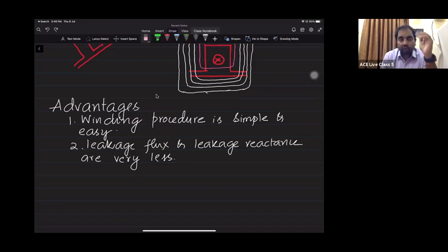So most of the flux lines cross the air gap, link with the rotor core and come back. As such, the leakages are less and the mutual flux lines are more. When the leakages are less, the equivalent leakage reactance is also less, the power transfer to the rotor will be more, and the torque will be more. I hope this is clear. Confirm me all of you.